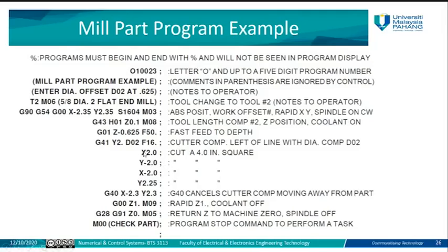We have already one G code here, G01, then G41, and all the coordinates in between will be affected by the previous movement, which is G01, or linear profiling. So linear profiling will be applied on all these coordinates: x2, x -2, x -2, y 2.25, and so on, until the compensator is cancelled by G40. So G40 will cancel the cutter compensator here.